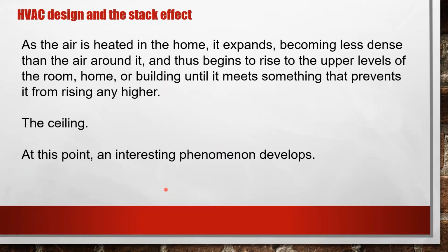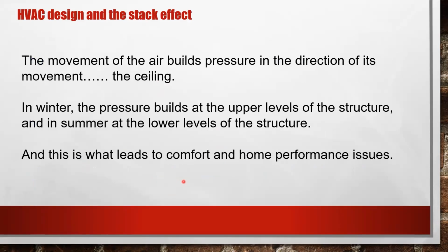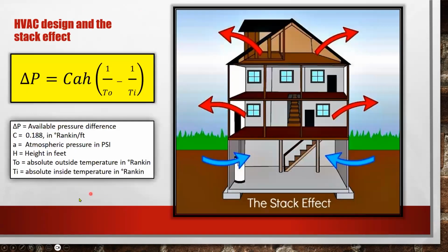At this point, an interesting phenomenon develops. The movement of the air builds pressure in the direction of its movement, the upper ceiling. In winter, the pressure builds at the upper levels of the structure, and in summer at the lower levels of the structure. And this is what leads to comfort and home performance issues. And anyone who's ever lived in a 2-story house knows it is always warmer upstairs than it is downstairs. And that's where the stack effect comes in.